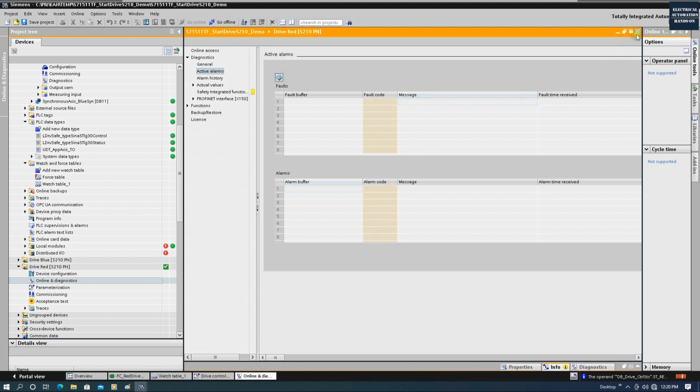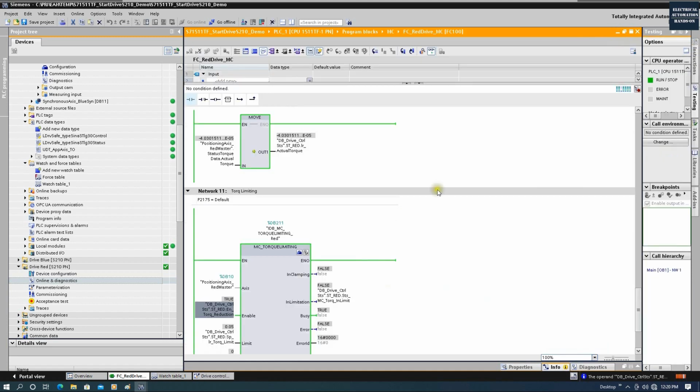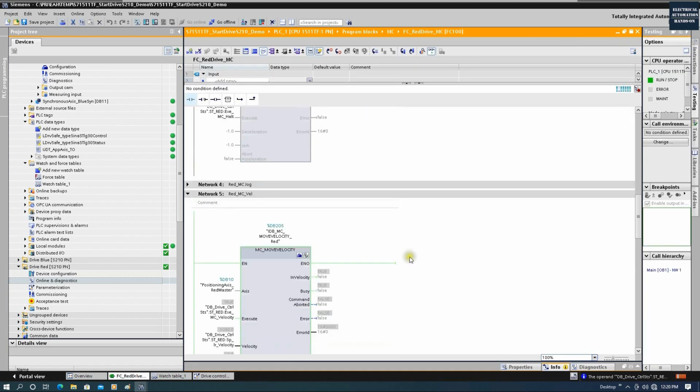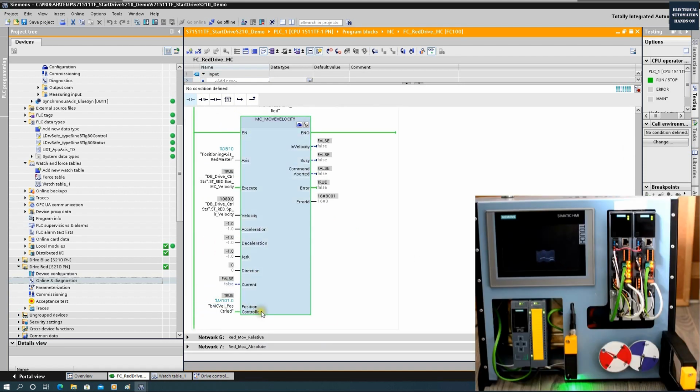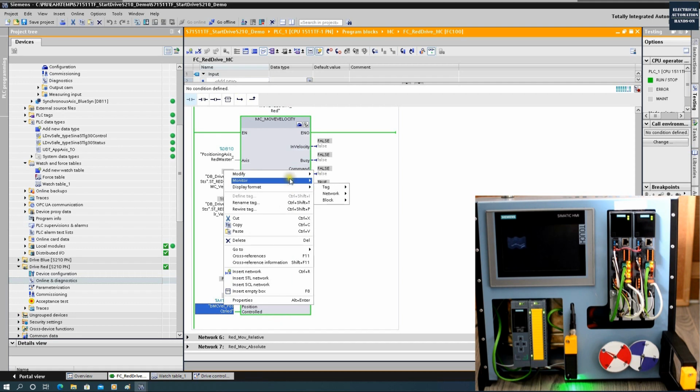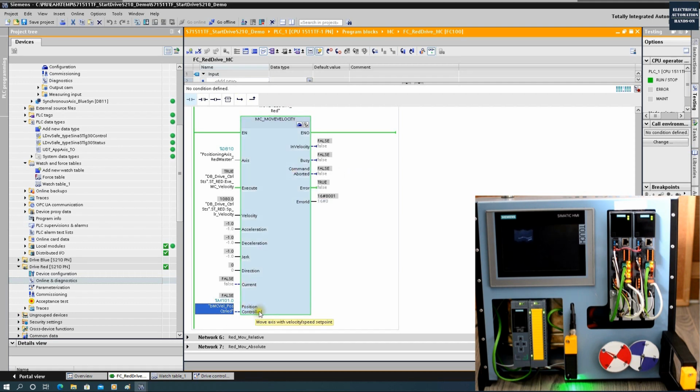Firstly, let's acknowledge that this actually comes from the move velocity command. So let's go up. That actually comes from here, this position control. While we are using the torque reduction and we fire the move velocity, we need to turn this off, so kill the position closed loop. Because while we are jamming the motor, the internal set point is still working, but the feedback actually stops and is jammed there. Once I release, the set point and the feedback apply a huge error to the positioning closed loop, and then the motor will run very fast. So while we are using the torque reduction, keep in mind we need to turn off this position control. Let's leave this off.